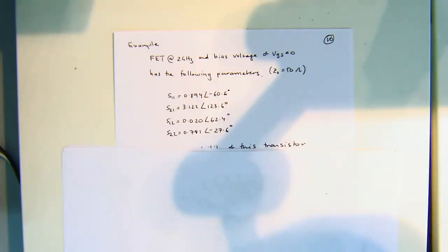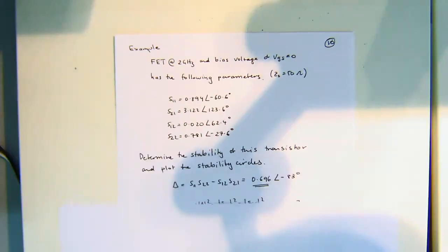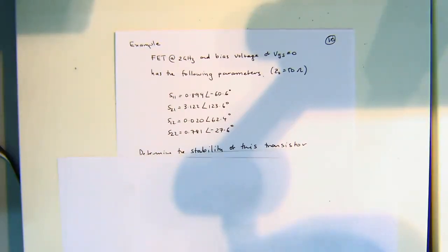Just one step. To those parameters, we calculate our G value of CL and R. Not yet, not yet. First we want to work out if it's going to be stable, right? If it's going to be unconditionally stable. K and delta. Perfect.